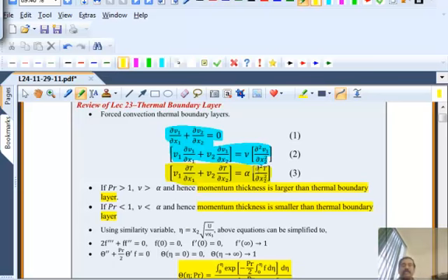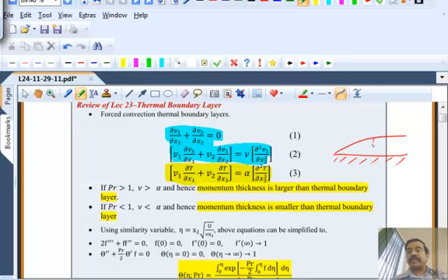your boundary layer equations. And the basic idea is that when you have a boundary layer near a plate or near a solid wall, you will have a thin region over which a sharp temperature gradient or sharp concentration gradient would occur. And that is what we will call the thermal boundary layer thickness, which could be different from the momentum boundary layer thickness.